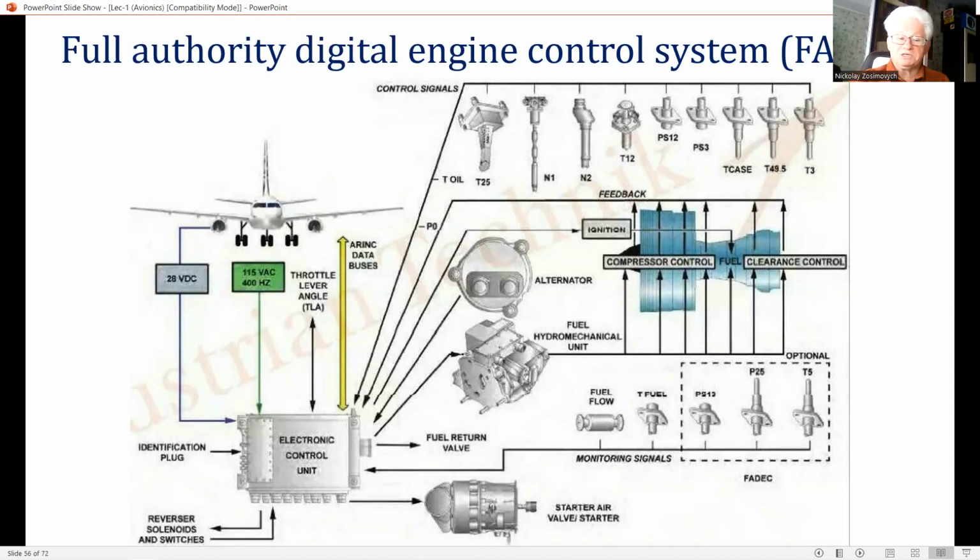The system has what is known as full authority in terms of the control it can exercise on the engine, and a high-integrity failure-survival control system is essential. Otherwise, a failure in the control system could seriously damage the engine and hazard the safety of the aircraft. A FADEC engine control system is thus similar in many ways to an FBW flight control system.